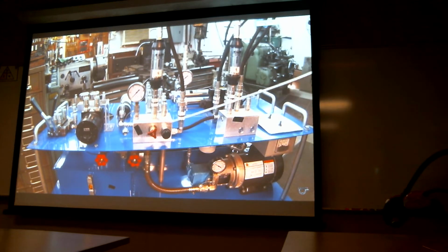The biggest failure that I have with these relief valves right here is the wrong pressure range. All right, if I'm going to operate my hydraulic system at, say, 1500 psi, and I get a relief valve that goes from 0 to 800 psi, what's going to happen is every time you turn that system on, your fluid's going to dump over your relief valve, and nothing's ever going to happen out here. Okay? So it's very important to make sure your spring range is correct on your relief valve.